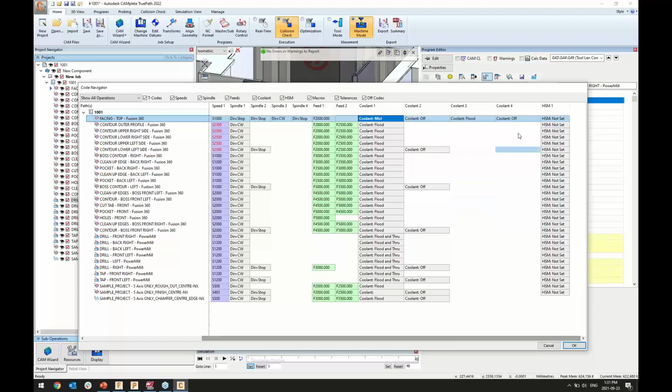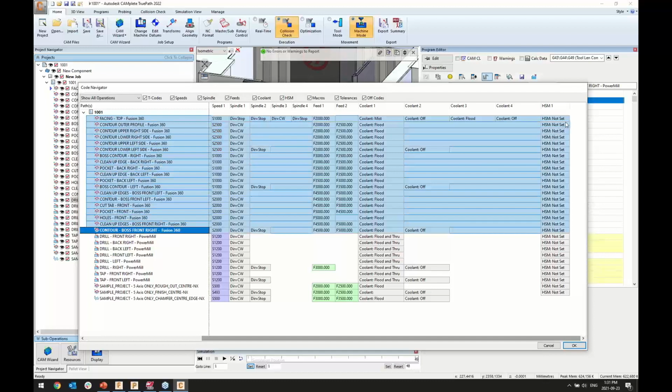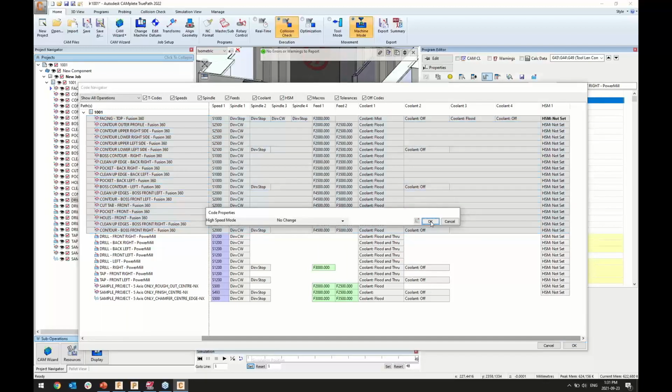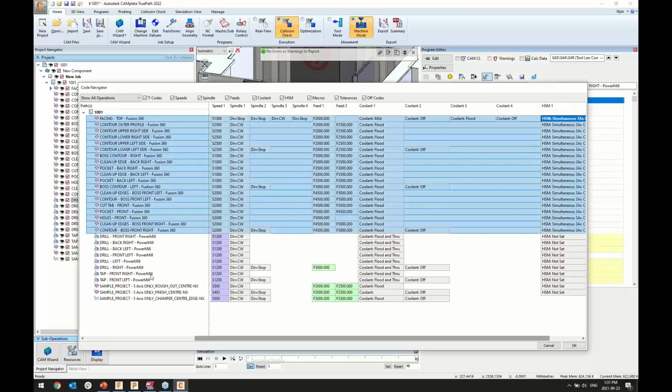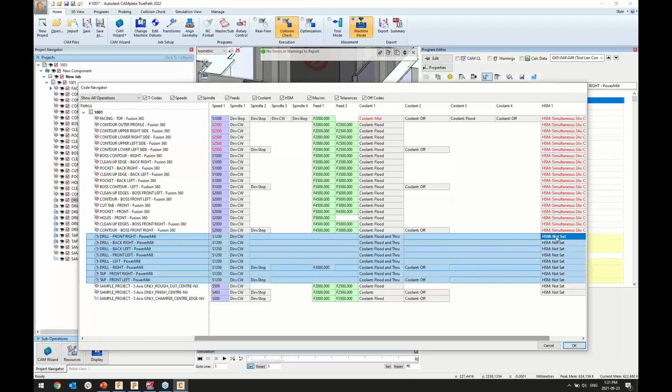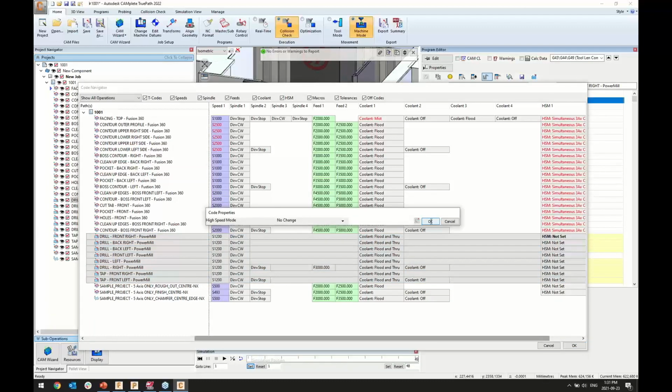And ultimately, also now being able to start adapting some of those machine behaviors to the machining operation that we're trying to do. So the first few operations were really focused on 3-axis roughing and really being able to plunge the tool into the material and remove as much material as possible. So really focus here on 3-axis roughing operation. If we look at some of those drilling and tapping operations, at that point, the objective of the cut will be slightly different than a 3-axis roughing operation.